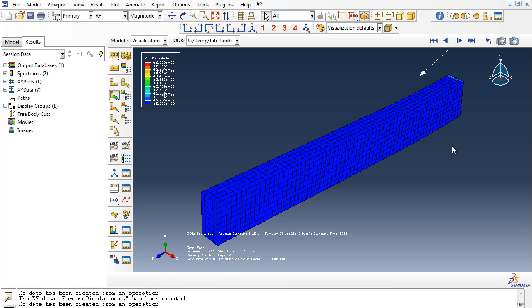That creates extra steps in the analysis where you have to create the FRP or the natural fiber reinforced polymer. Then you have to create a contact condition between the FRP and the beam.